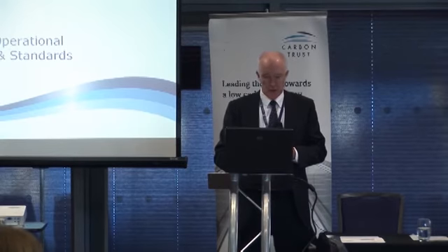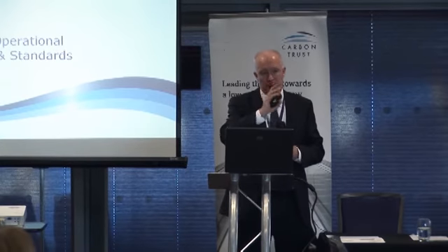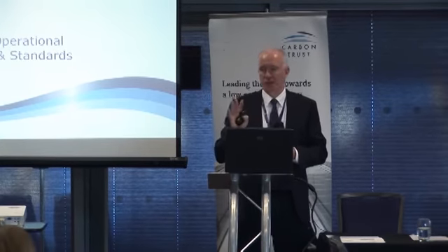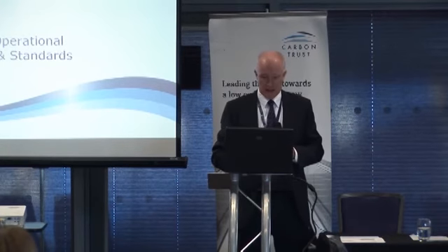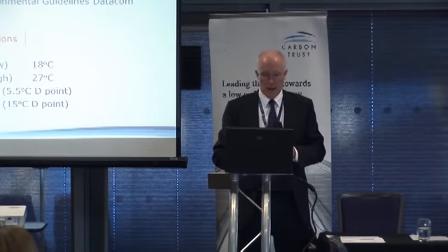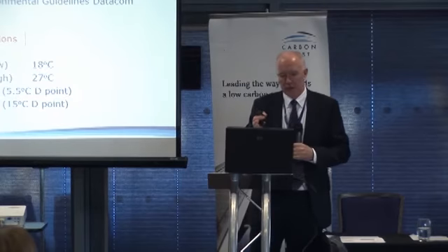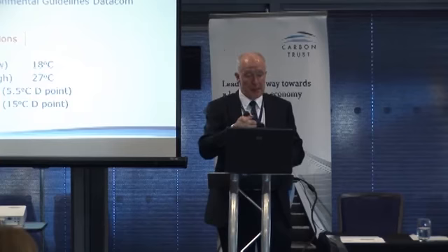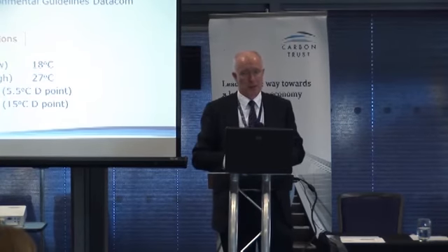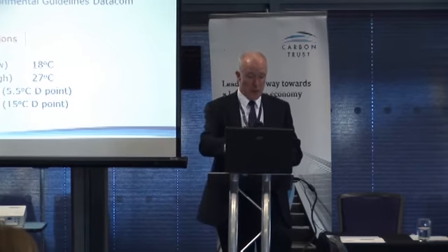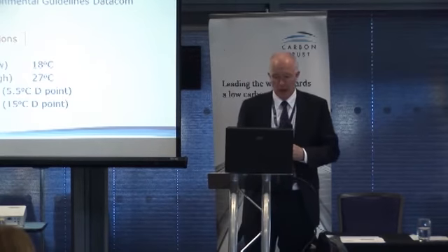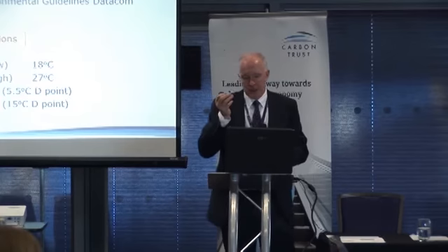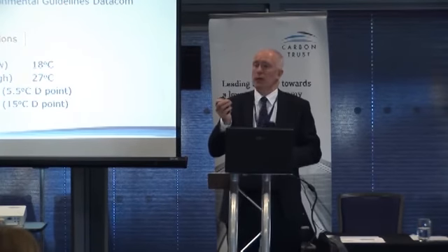Perhaps looking at your operational standards, and this came up a little bit earlier, what temperature and what humidity do we need for our data centers and our network server rooms? The EU Code of Conduct for data centers is worth looking at, but perhaps the Americans are ahead on this. The ASHRAE environmental guidelines for datacom equipment are excellent, and that's where some of these guidelines come from. Importantly, is to get an understanding here.